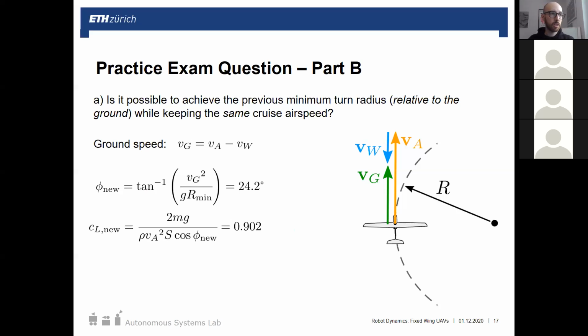More specifically, where it might be defined for a small UAV, at least practically speaking with your autopilot, is just wherever the IMU is oriented. So generally, again, you try to orient the IMU such that the X body axis is out the nose of the plane because we want it forward facing. What the autopilot is concerned with is, okay, my IMU is telling me I'm oriented like this, and it doesn't make too much sense to try and put your IMU at a weird angle and then compensate for it, because this is very hard to measure.